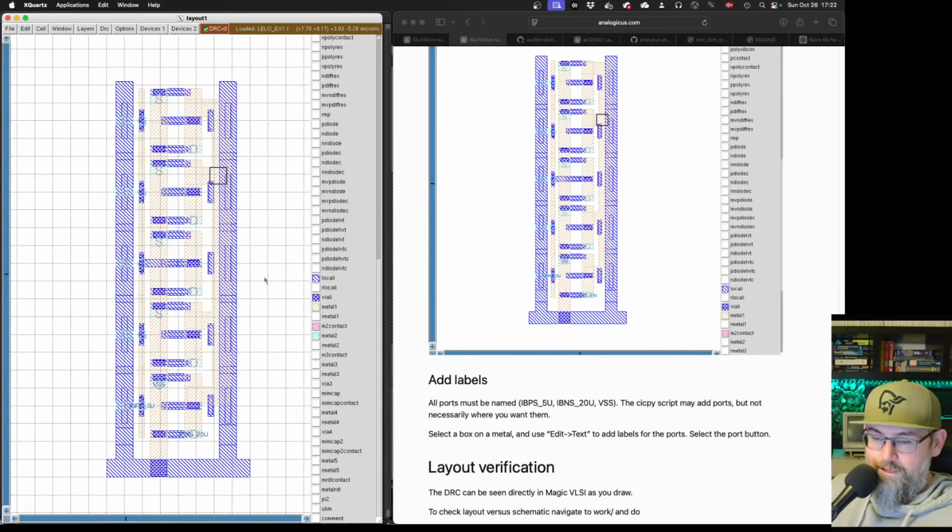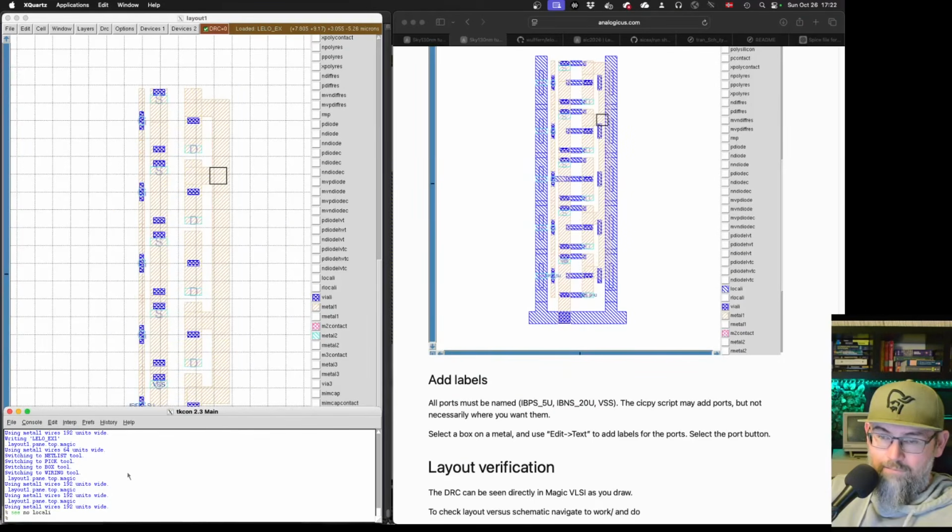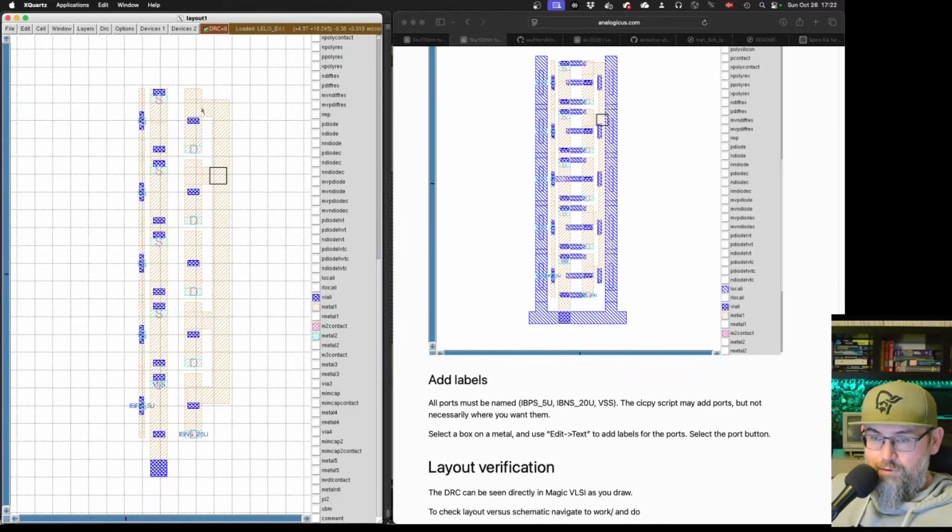Now I broke that rule right now. It might not be easy to see, but see no local interconnect. So here you can see I broke that rule. I went horizontal and then vertical in metal 1. But that's okay. There's no way I'm going to go through here with another metal. So that's okay. I can't get through there anyway. Not always do you need to think too much about the decisions. Now this placement that I've done, you will see that it adds the ports by itself. Yeah, and I think I'll keep them like that.